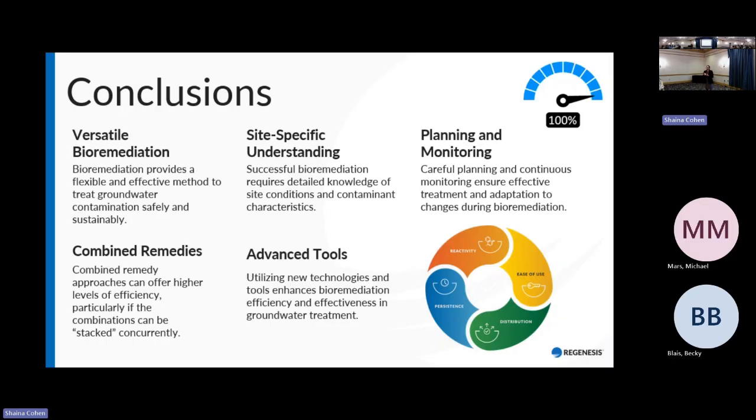I mean, there's a wide degree of variability of experience and skill amongst the consultants that I work with. I don't want to bash anybody, but I'd say most folks are able to interpret that data at least superficially in a way that makes sense to them, and at least be able to say, okay, the ORP I'm getting here is minus 400, but I added an oxygen releasing compound, so that doesn't make any sense, right?